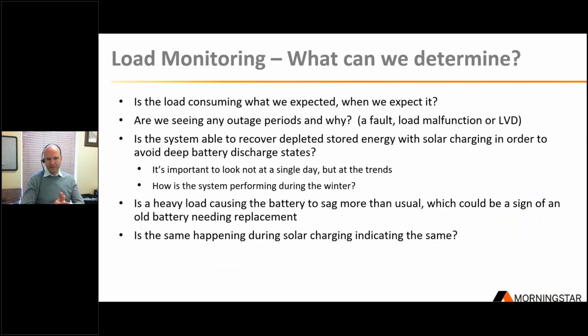So some other questions that could be asked are, what is the load consuming? Is it what we expected? Did our load profile reveal the true nature of this load? Or were we seeing some surprising effects? Are we seeing outages? Is the system going into LVD? It's not always a dead battery.